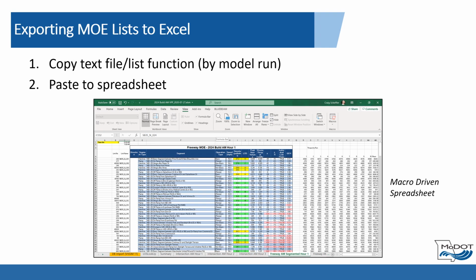It is important to note that the level of service data derived from Vissim results is not directly applicable or necessarily reproducible by a similar analysis using Highway Capacity Software deterministic methods. For that reason, it is common to designate level of service results from micro-simulation programs as LOSS, or Simulation Level of Service.